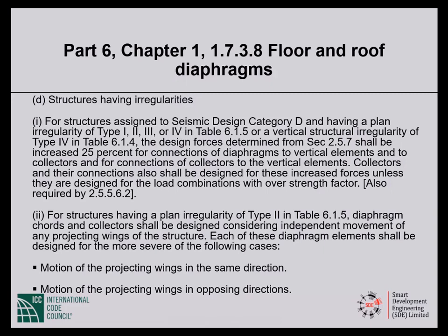So, design forces shall be increased 25% for connections of diaphragms to vertical elements and to collectors.